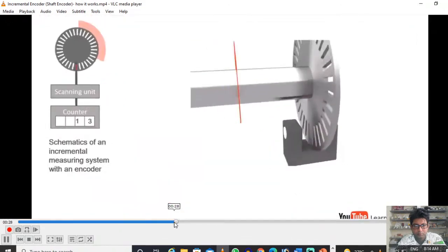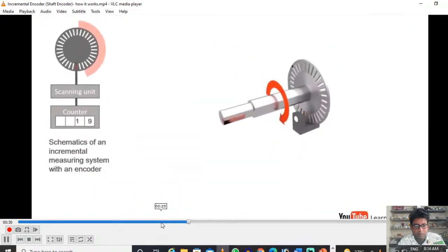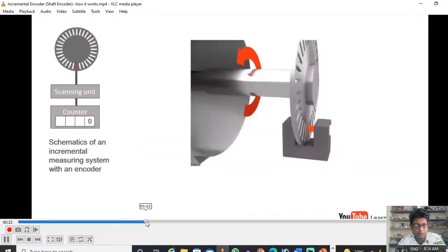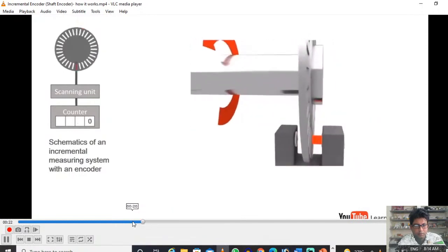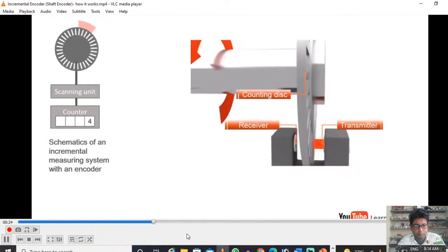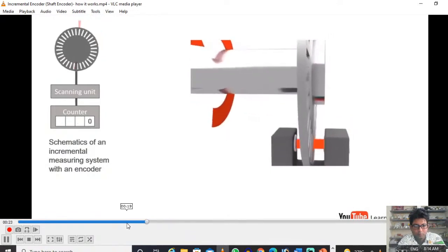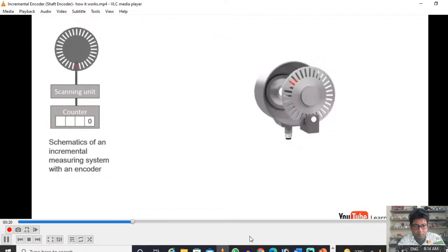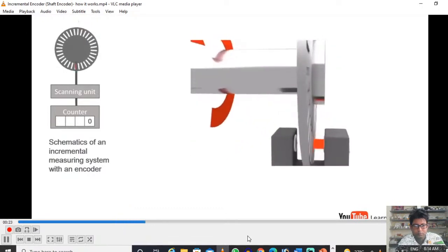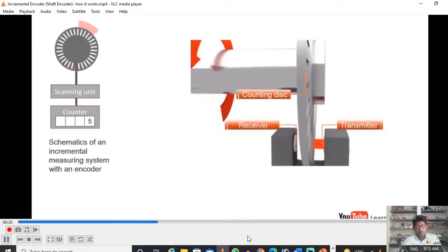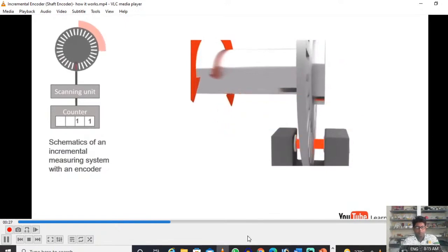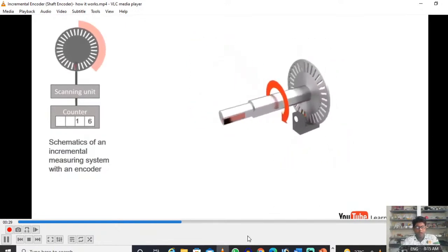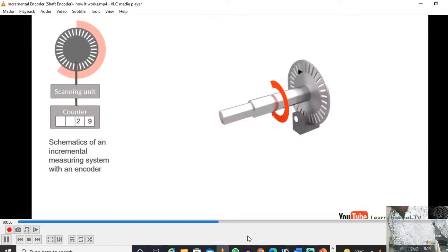This is a so-called shaft encoder that generates a sequence of pulses. A light-emitting diode serves as sender, and its light is detected by a photodetector. Therefore, the encoder has transparent sections that are equally spaced, and it can generate a sequence of pulses. The output is measured in pulses per revolution, which can be used to determine either the position or the rotational